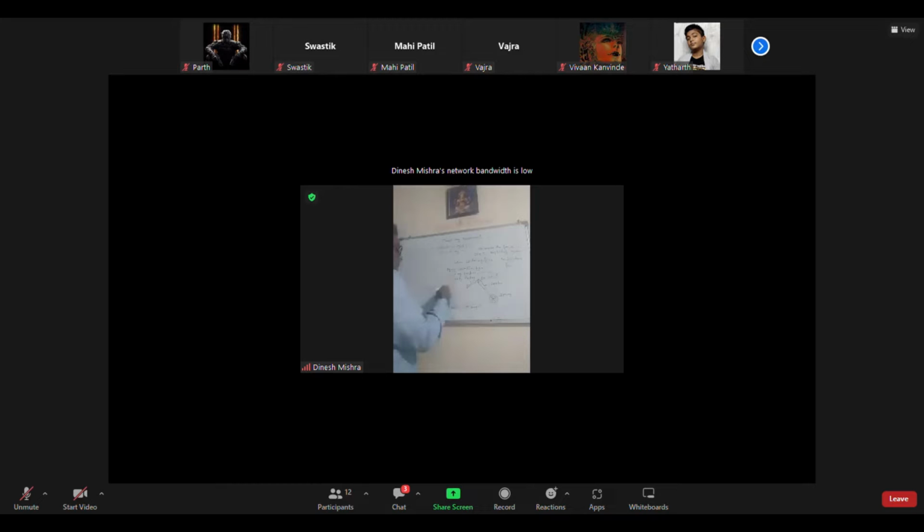But at the same time, the spring gets wound and produces a force in the opposite direction. When the deflector deflects, the spring is wound and it produces a force. It is opposite to what? Deflecting force. So when the spindle starts rotating, at the same time the gravity weight is also lifted.